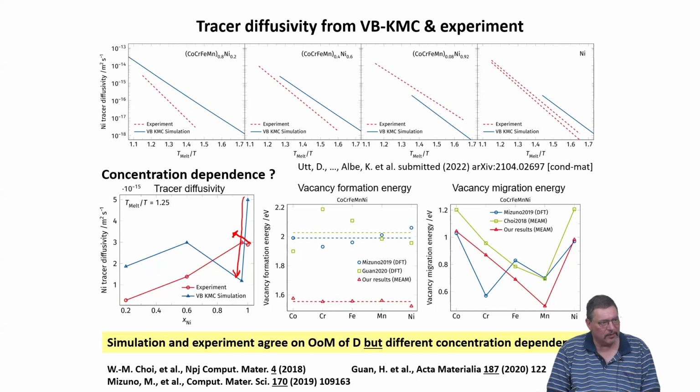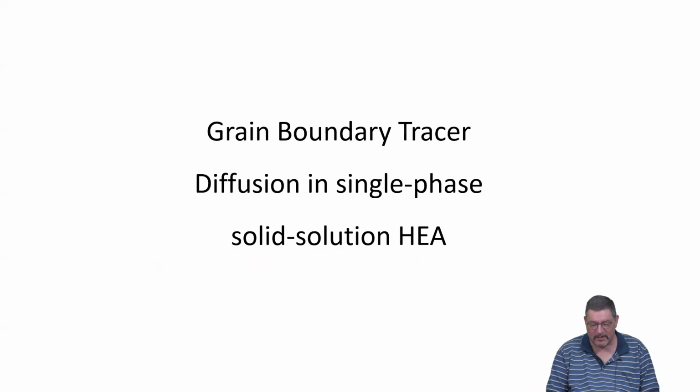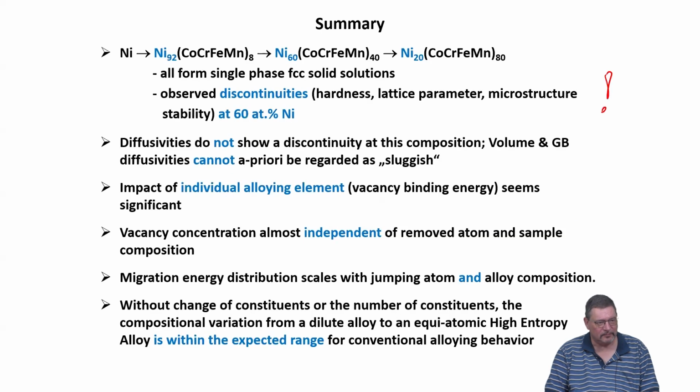consolidating what we knew. And they basically confirm each other in that there is no change going from dilute solid solution to high entropy system, which is outside of the range you would expect. There is no change in vacancy concentration. There is no real change in macroscopic diffusivity. There is no discontinuity. This is maybe very important. So it means volume diffusion is unaffected. This is, I think, now confirmed.